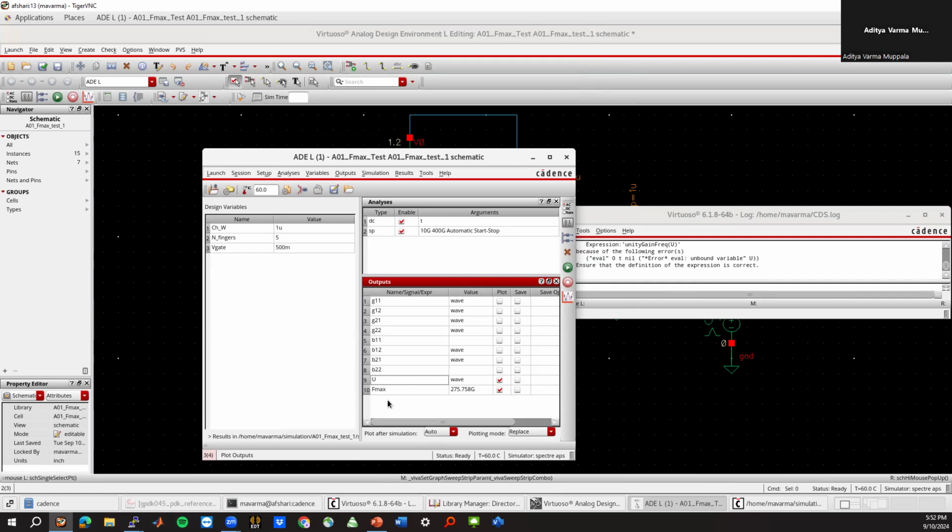And then another thing which we will use in a future video is the different dielectric and metal layer thicknesses and conductivities, things like that. And in case there's any shrinkage factor, like a 90% shrinkage factor in different processes, that needs to be kept in mind. And you can also look at the different performance metrics. So go through all the documentation, and then as a first step, you can just pick a transistor of your choice, try different transistors and simulate the fmax for different bias conditions, different gate bias, different VDDs, and for different sizings, different finger sizes and number of fingers. So you can play around with that and see.